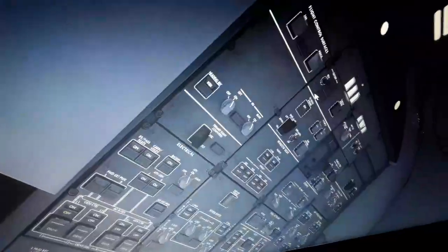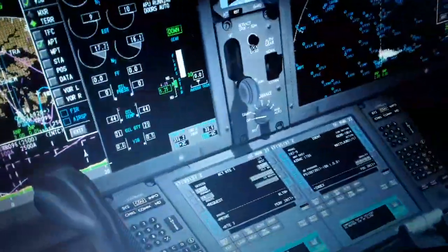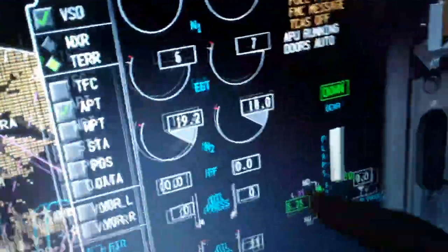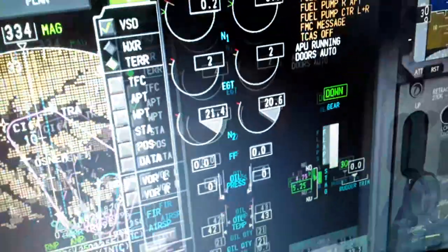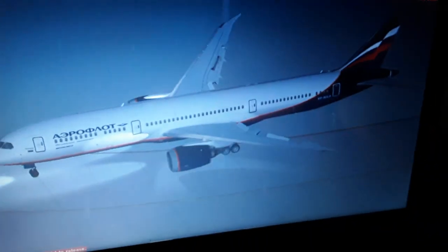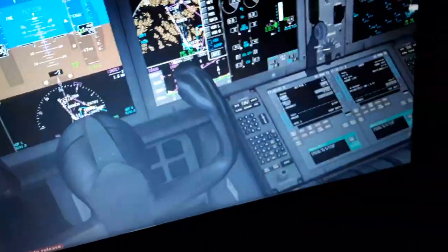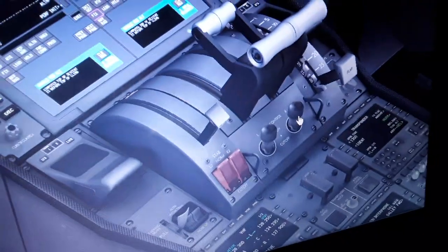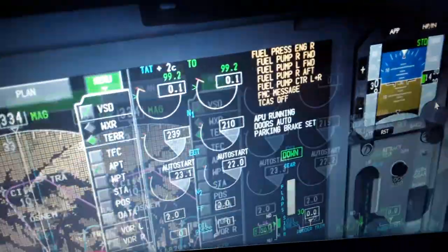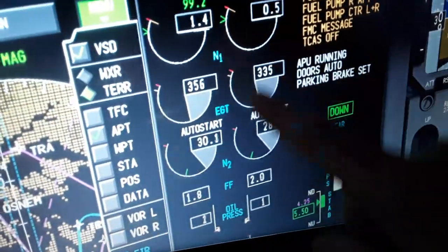Very quickly. You're gonna see now we're gonna have pressurization from the APU. The auxiliary power unit is gonna pressurize the engine starter to above 25%. We can start the fuel flow. So you can hear we have only pressurization right now. So we let the fuel control both on position. So you see now we have the auto start coming in. Auto start open. All systems now of the engine.